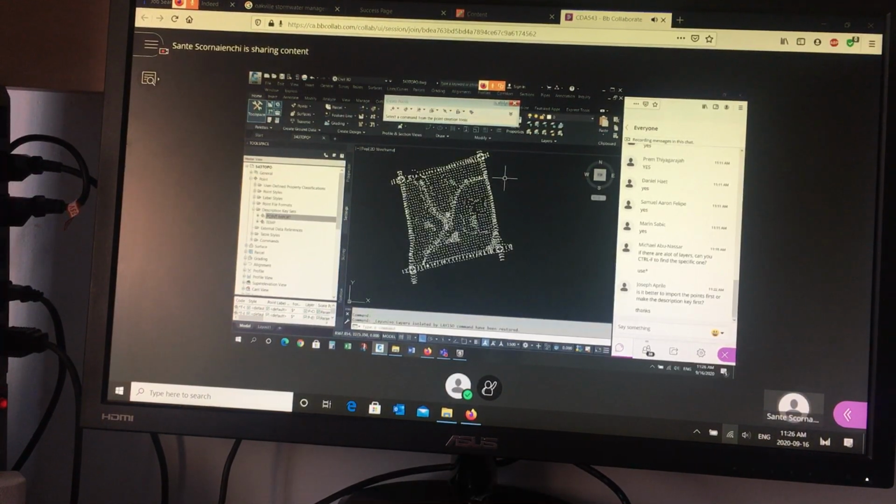Now, it sounds like a simple thing, but if you had to go through your CSV file, take all the trees, put them in their own file, and take all the center lines, put them in their own CSV file, and have a CSV for each description, and then set the current layer. It'll come in on the tree layer. Set the CL layer. It'll come in. You could get away with not using the description keys, but it's certainly a handy function to have. Okay, so does everybody understand what description keys are and what they do?